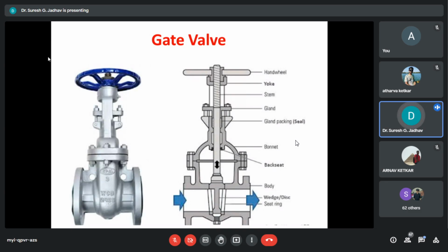If remote operation of the valve is required, then this could be achieved through motor with limit switches. Proper selection of the drive unit should be done depending upon the services. Now next component is bolting. Normally high tensile stud bolts are used for bonnet bolts and low carbon bolts for gland and yoke boltings.